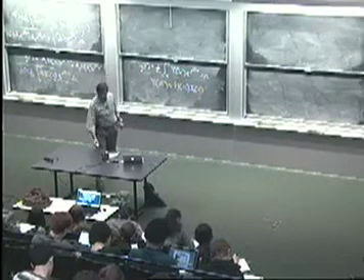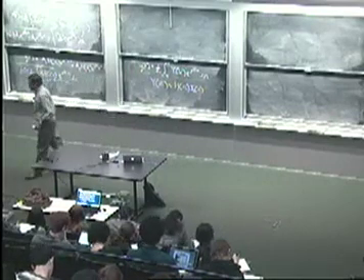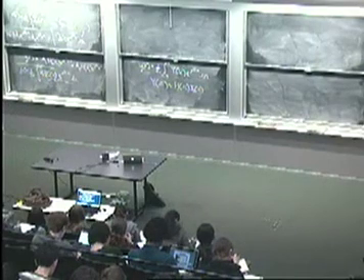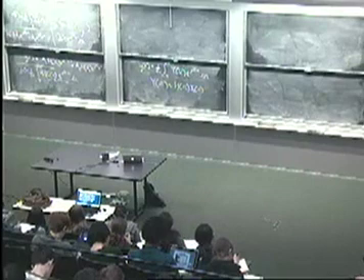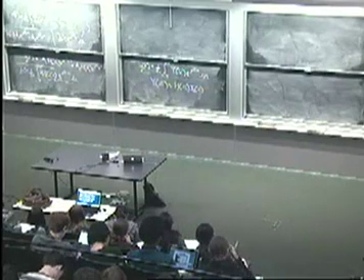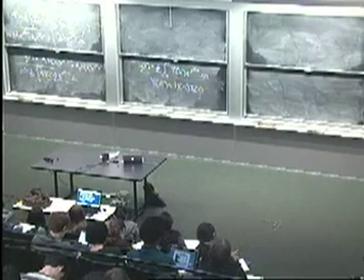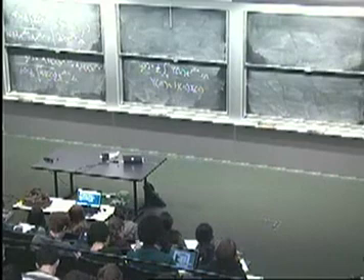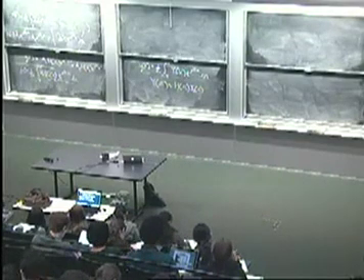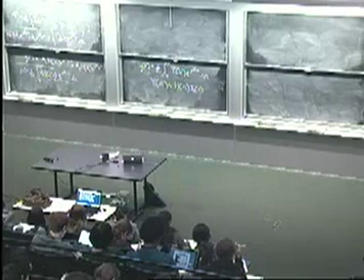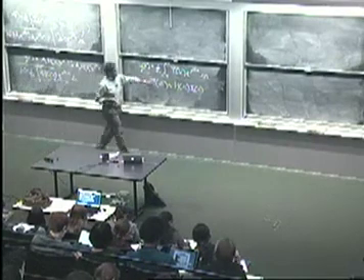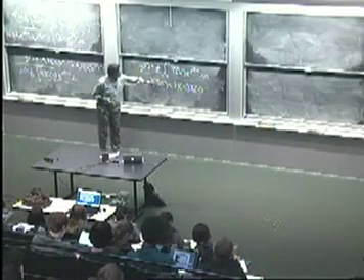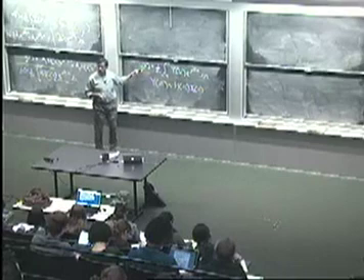Okay, so we've done a complete analysis of the input-output response of the system for essentially an arbitrary input with just a simple multiplication. So look what we've done. We've taken the input that we were given, computed the DTFT of it, which gives us the spectral content, and I'll spend some time giving you intuition for that. That's the spectral content of the input signal. What we've discovered is that the spectral content of the output is the spectral content of the input scaled by the frequency response. Okay, and once you have the spectral content of the output, you can reconstruct the time domain